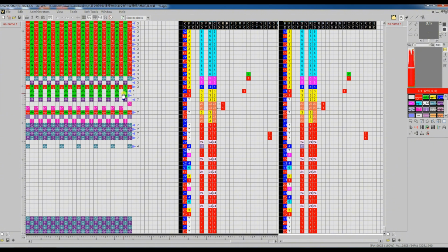Then 1 row of 1x1 ribs is knitted with the ravel yarn feeder 7, followed by 1 row of 1x1 back stitches. Feeder 7 is then brought outside the knitting area, and feeder 1, the drawn thread feeder, is brought in to knit 1 revolution of 1x1 back stitches. It is then brought to the default position as it is no longer required.